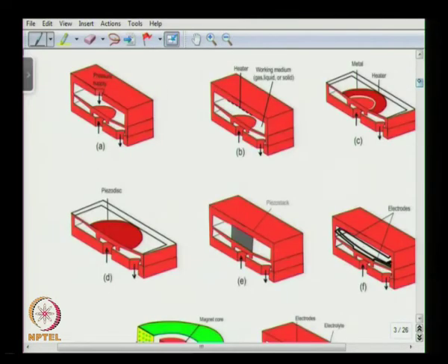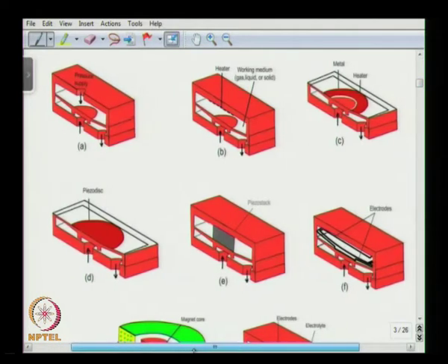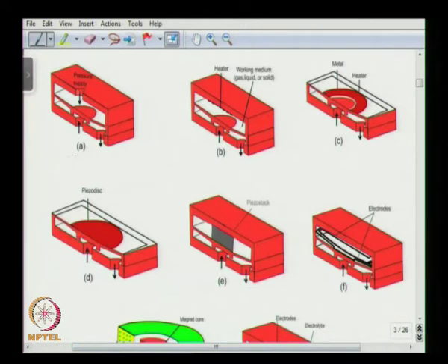Okay. So, let us first look at the designs of different types of microvalves. This is a pneumatic microvalve where this is the inlet connected to the external fluid source, and this is the valve actuator. This is the disc which is being actuated by external supply. When this line is connected to the external supply and the supply pressure P is greater than the spring constant plus the inlet pressure, then the valve would be in the closed state. And when this external pressure is taken off, the membrane goes back to its original position because of the spring force. So, the valve is open.